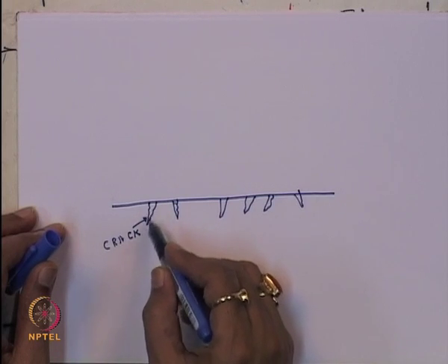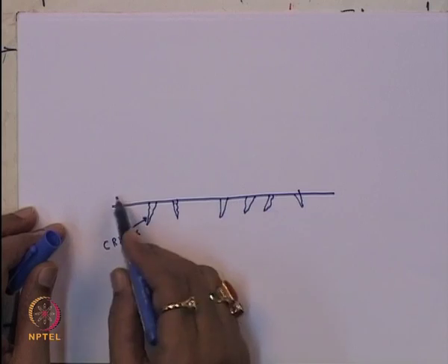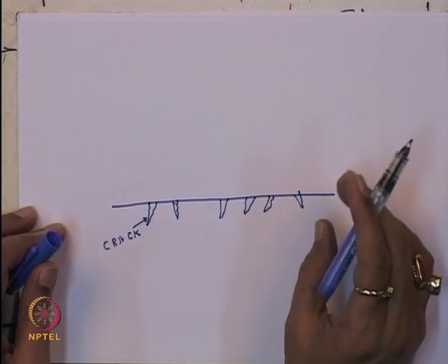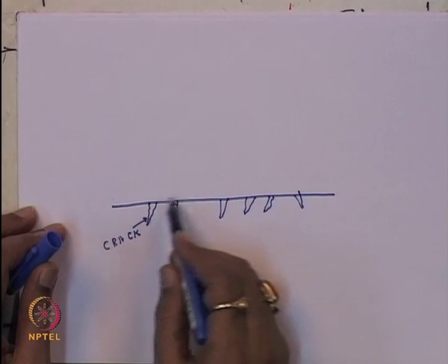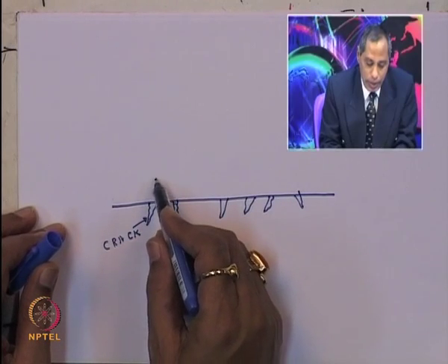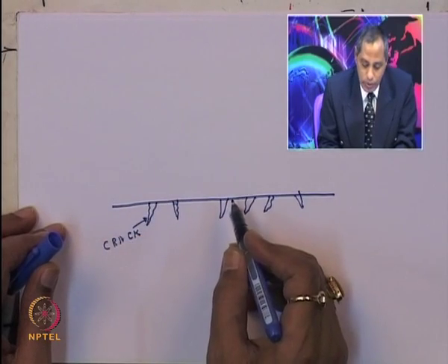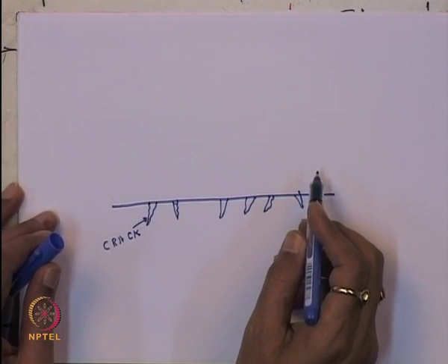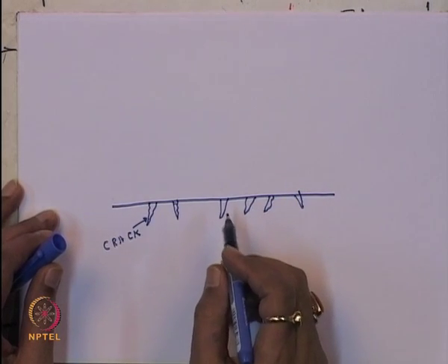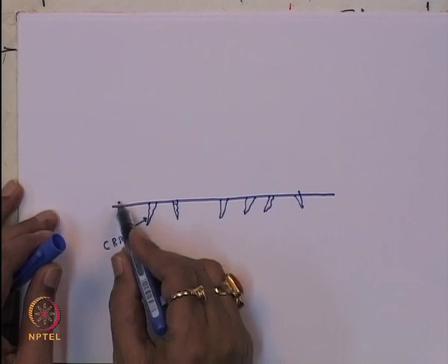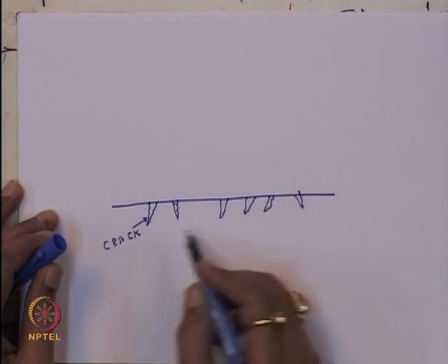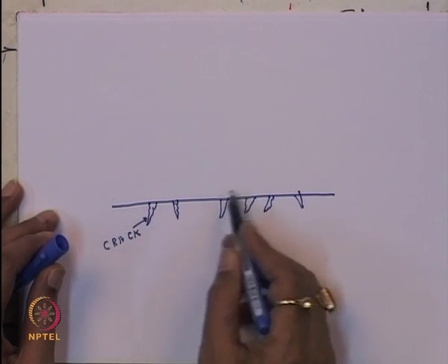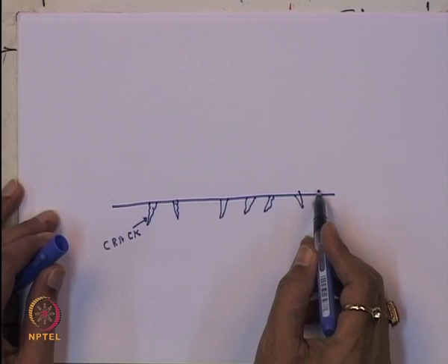So, we provide the bituminous overlay, in general ranging in thickness from 25 to 100 millimeter in the traditional method, and the crack in the original pavement then reflects up through the new overlay. So, again there is a possibility for the formation of cracks on the surface of the road. Therefore, it is required to provide a strip of geotextile placed over this crack. You have to place a layer of geotextile material at the top of this crack.